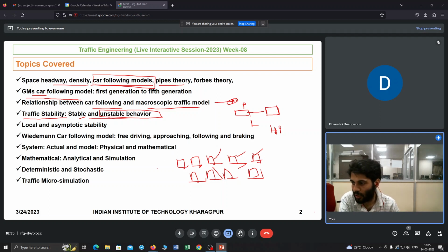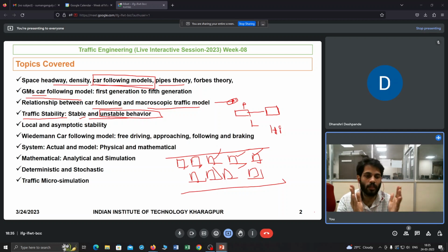Whenever you are impacting the traffic in a serial order, like if your vehicles are less spaced, and travel speeds are relatively high, in such a case, if one vehicle is creating some kind of nuisance as a lead vehicle, then it can impact a longer chain of vehicles, right?